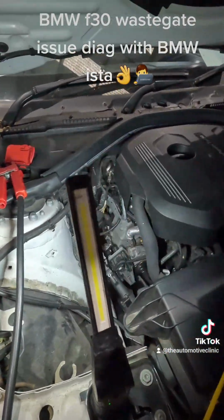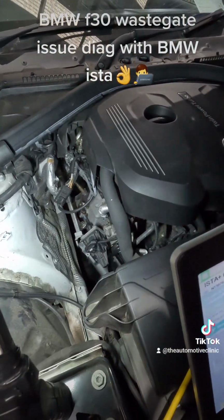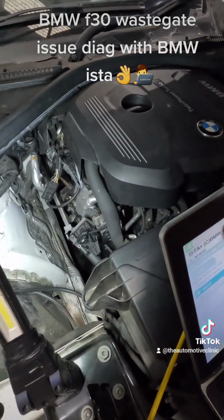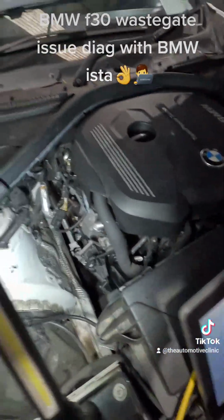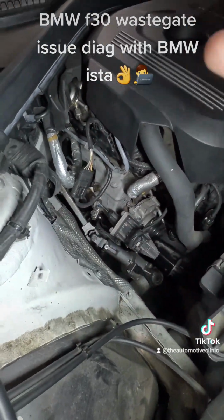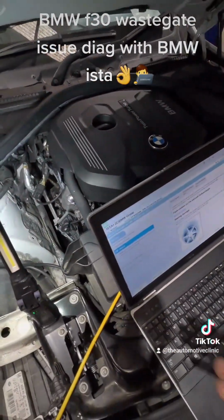We can check for physical damage and things like that in there, but we can see that the wastegate is actuating, the computer's got control of it, we can see the positions are reading as well. The adjustment is correct on it, so the adjustment actually hasn't moved, which is fine, but it has got a faulty turbocharger or wastegate system.